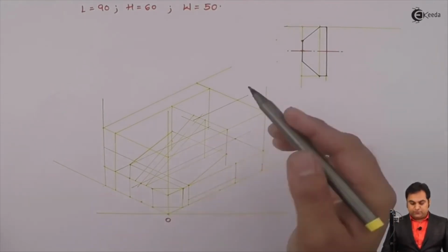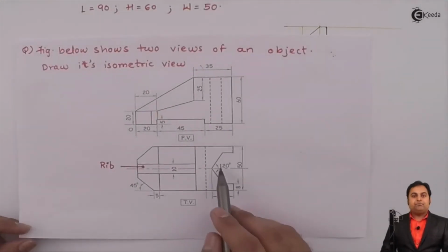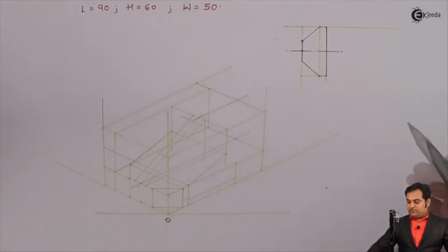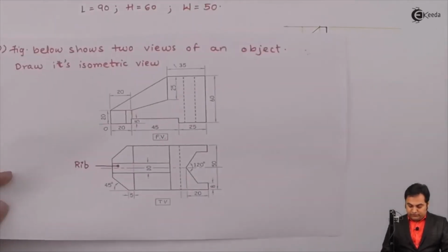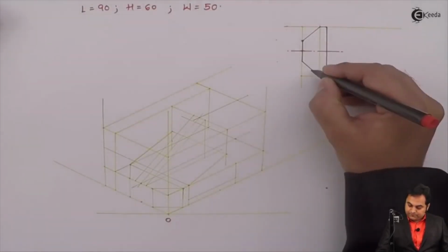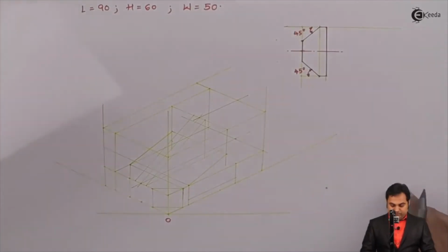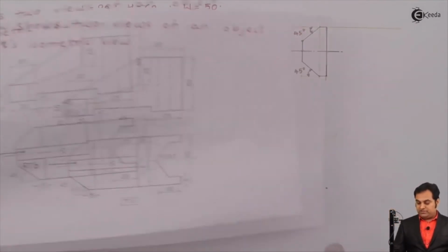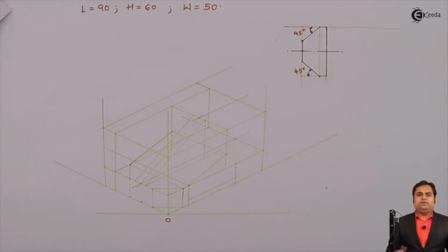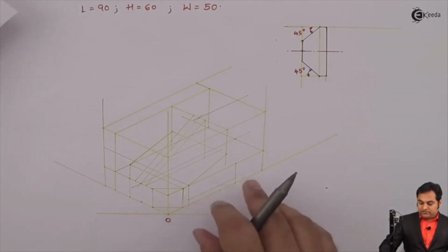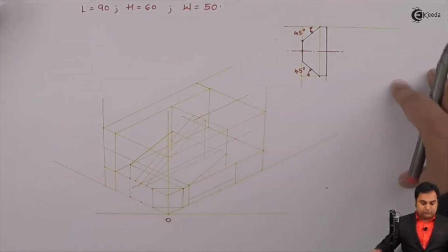now inside this portion there is a groove of 120 mm, and similar to what I had used previously here, the similar concept, that is 40 for the 45-degree surface. The same concept I would be using here for this 120-degree surface, which is inside this block, means we don't have to measure 120-degree directly onto the drawing because these are isometric drawings. Surfaces are already inclined, so it is better to draw the surface separately and bring it onto the drawing.